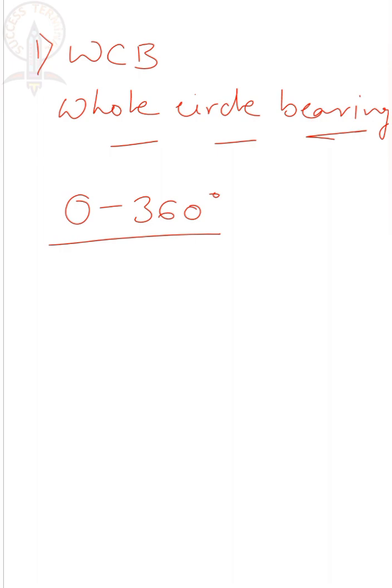Now, how are angles measured in surveying? In geometry, we use a horizontal line to measure the value of any angle. But in surveying there is no such horizontal reference. We use the magnetic north. Before magnetic north, you need to know what true north is. Before starting, we have to understand what bearing is.